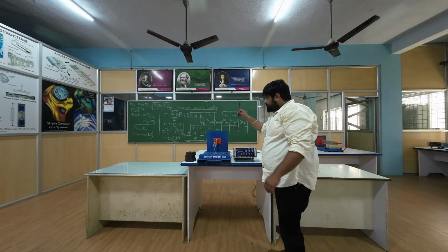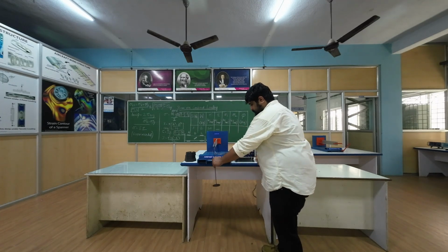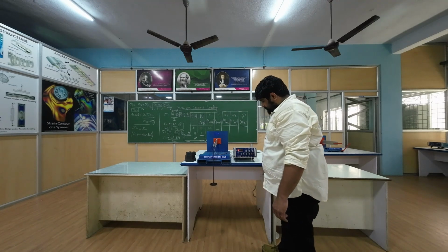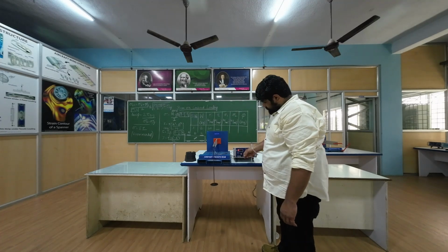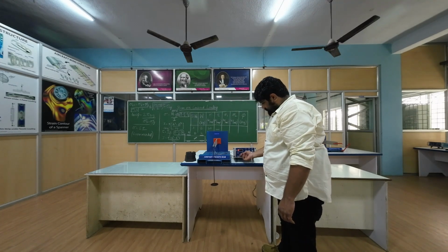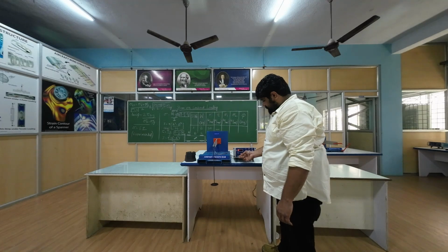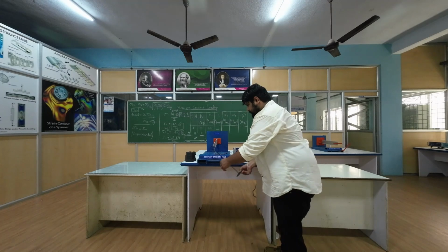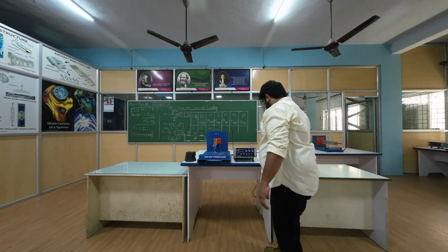Assembling the setup: first place the weight hanger at the tip of the beam, then switch on the experimental setup, choose the selector for the bridge, and then choose the coarse one for balancing the values. Once the setup is ready, you can go ahead, load and do the experiments. Dismantling: remove the hook, and switch off the experimental setup.